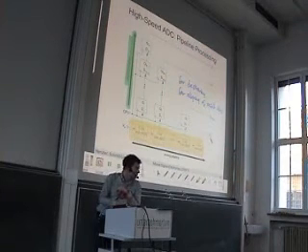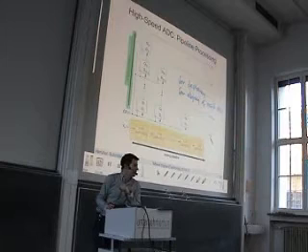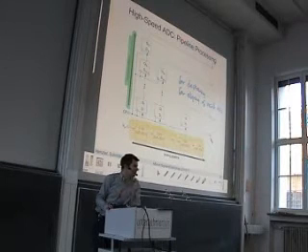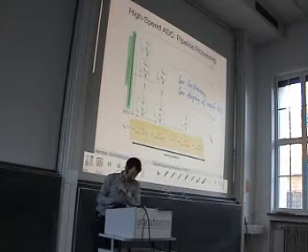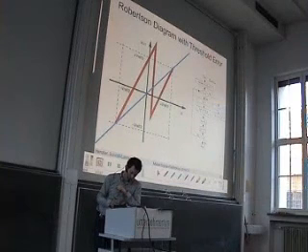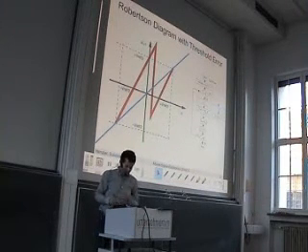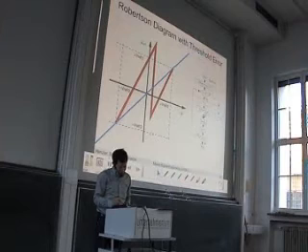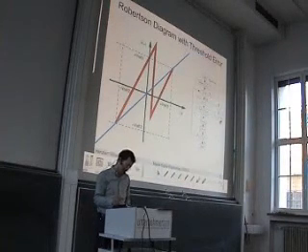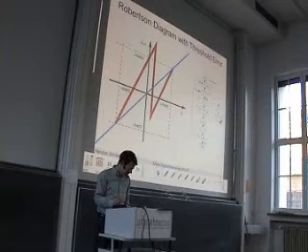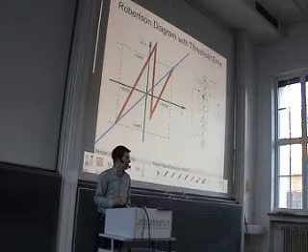Let me discuss now what happens in this algorithm if the circuit blocks are not ideal. So let's take a look at this algorithm. So here we subtracted Vref over 4, or we added Vref over 4. And our comparison was done with respect to 0.